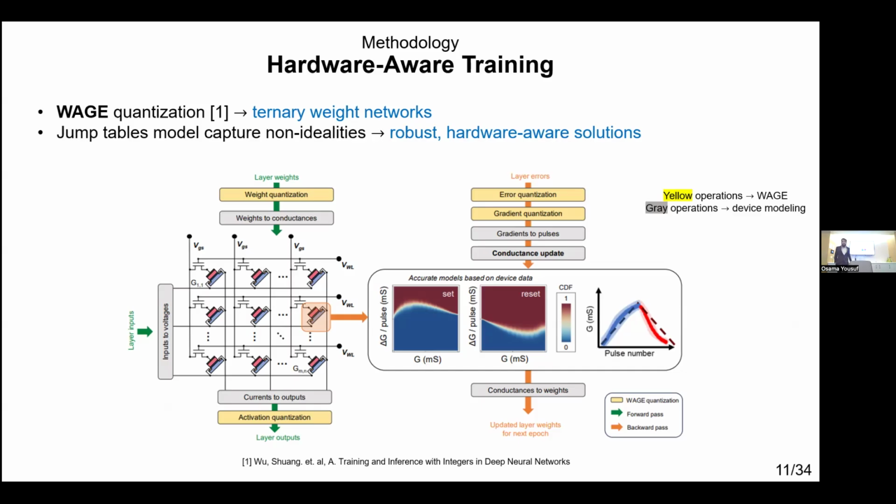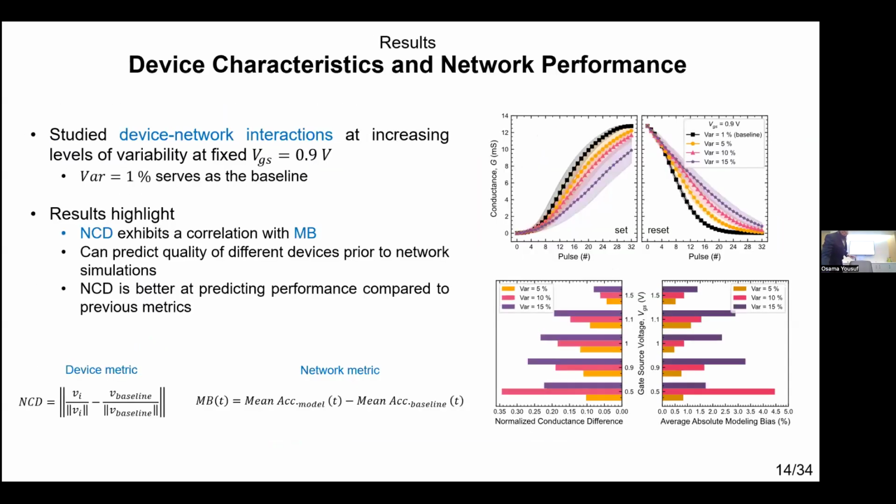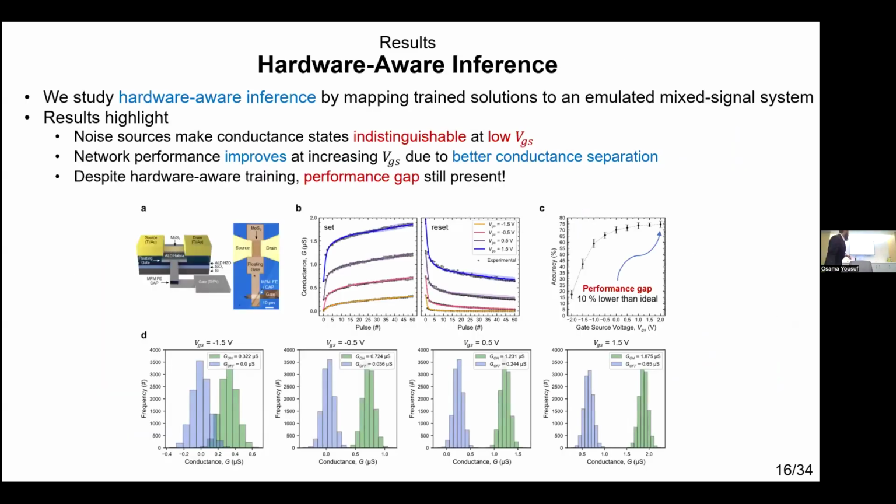Okay. But for the experimental part, those devices had other kinds of non-idealities as well, right? There is also a difference in your dynamic range by a lot compared to the synthetic device. So you can take compact model data that has a lesser or a higher degree of variability. In general, what we've shown is that if you compute a baseline for your hardware-aware network, it wouldn't have any device modeling operations. If you were to compute the performance and the loss landscapes, the networks we trained with our hardware-aware approach have flatter landscapes, so they're less sensitive to perturbations to the actual ternary weights. Okay.